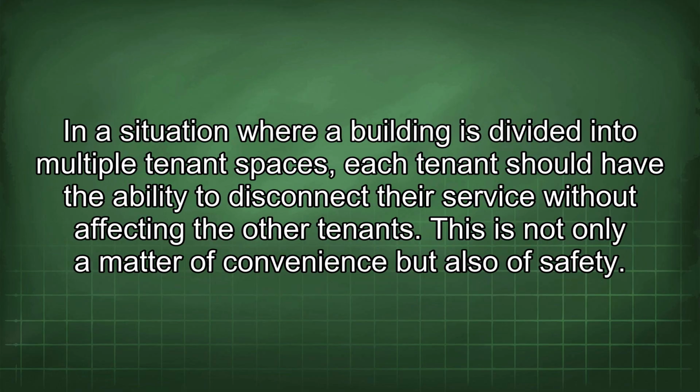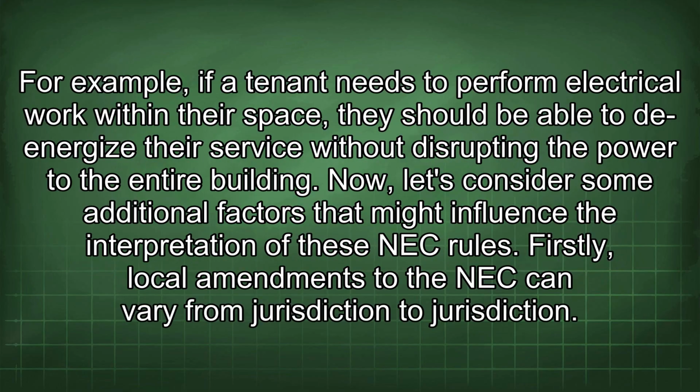In a situation where a building is divided into multiple tenant spaces, each tenant should have the ability to disconnect their service without affecting the other tenants. This is not only a matter of convenience but also of safety. For example, if a tenant needs to perform electrical work within their space, they should be able to de-energize their service without disrupting the power to the entire building.